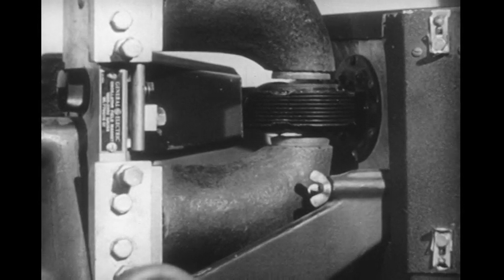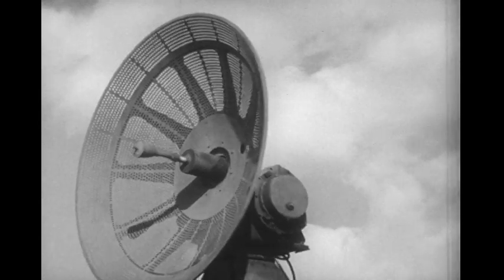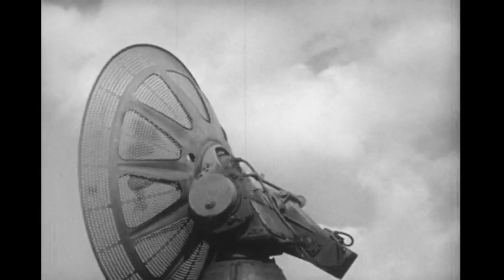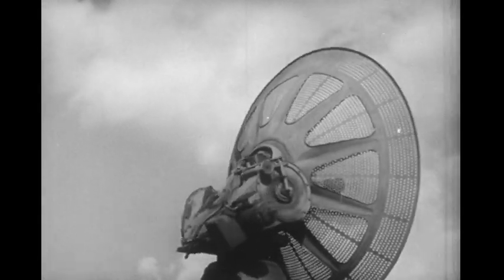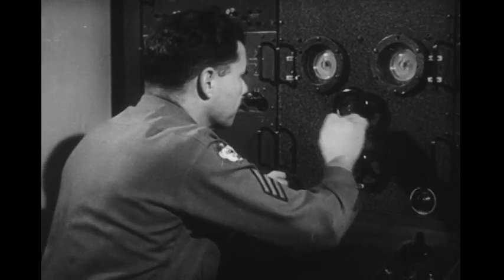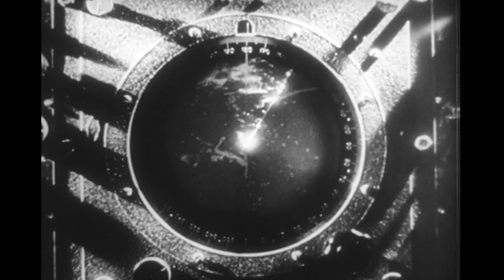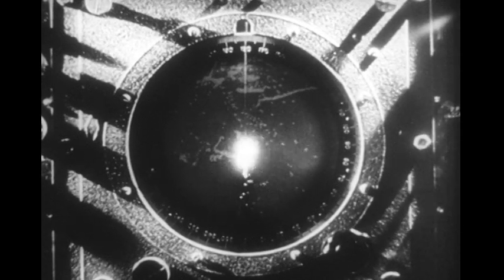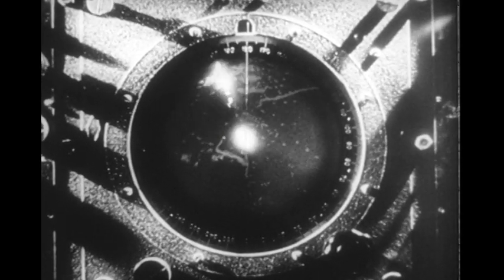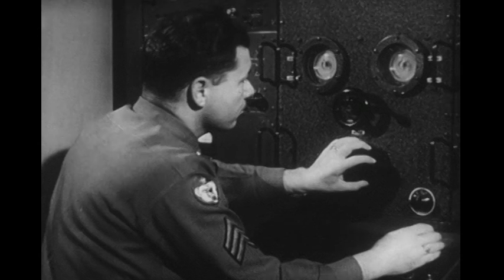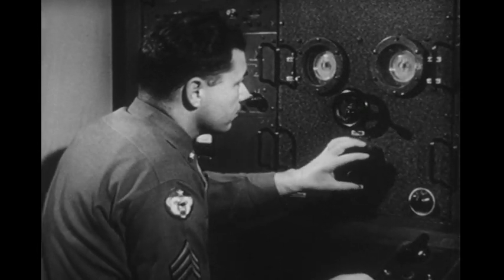We have seen how the pulse to be transmitted is generated. Now we will examine the second function of the radar set. The transmitted pulse must also be received and displayed. However, the signal which appears on the cathode ray tube must be at a video frequency which is much lower than the transmitted pulse. To produce this video frequency is one of the main functions of the radar receiver.